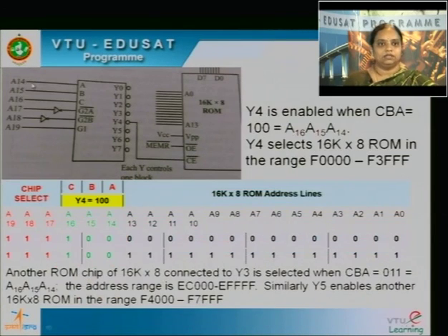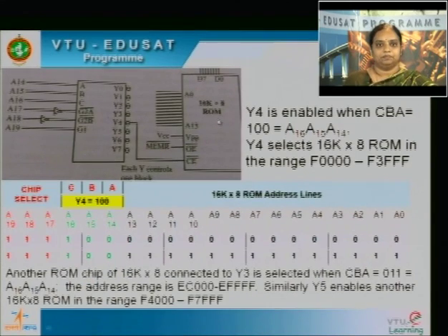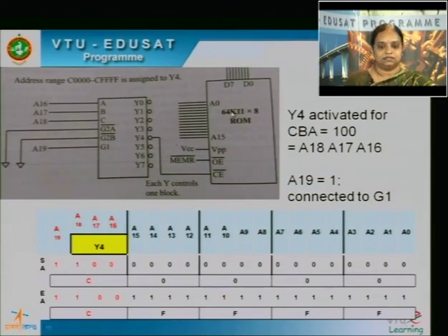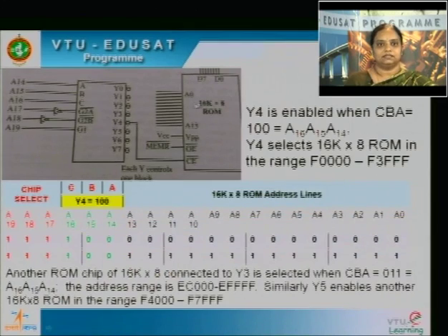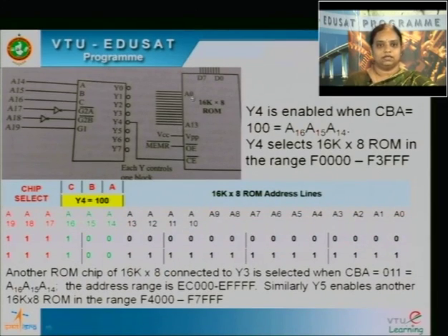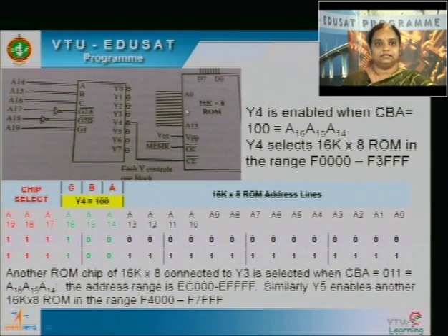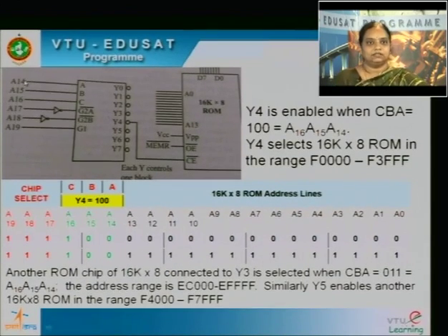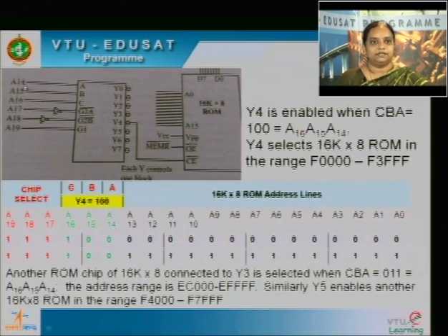We had another combination, this was your homework. Here we had a smaller ROM, that is 16K ROM. Previously we had 64K ROM. Here we had a 16K ROM. So this used address lines of only A0 to A13, that is 14 address lines, and the remaining address lines we had checked it here itself. So we had accommodated here only.